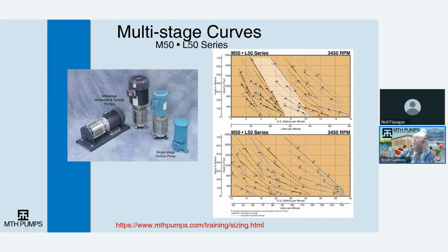One of the tables we have available on our website where we do show the curve family to be able to select is our M series. These are the pumps that can go up to 1,000 psi. They are based on a T51 impeller and water channel. So a single stage M series theoretically is the same pressure and flow as a T51. It's when you start adding stages that make it the higher pressure.